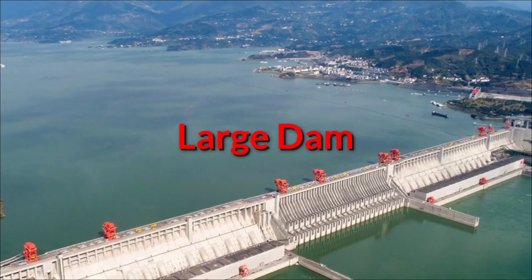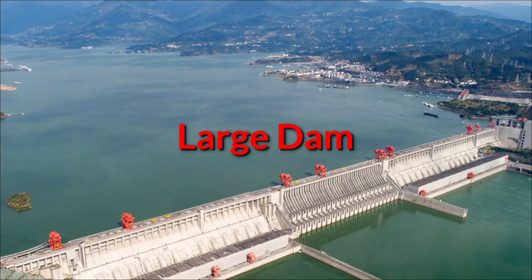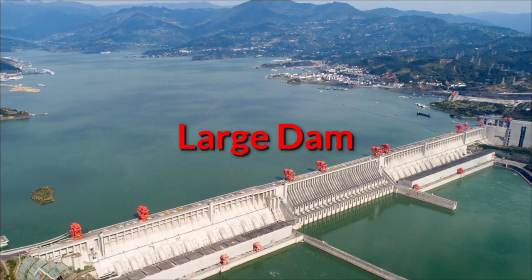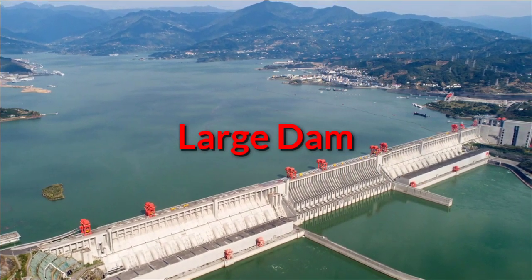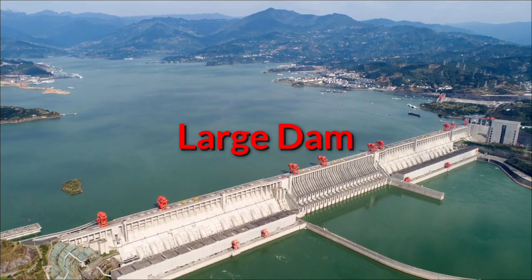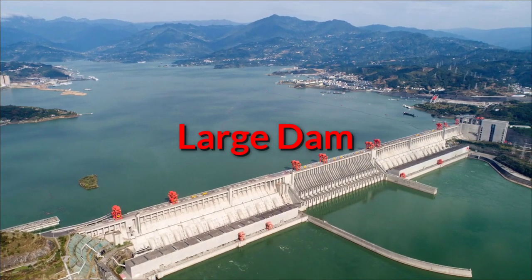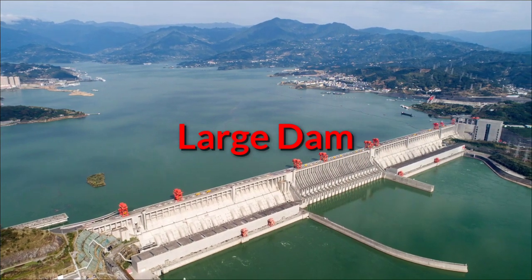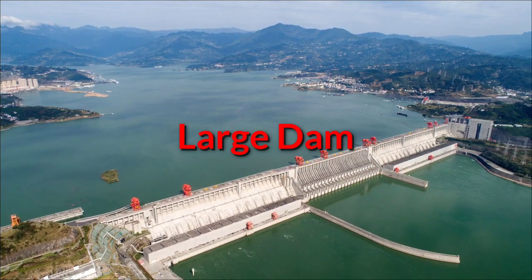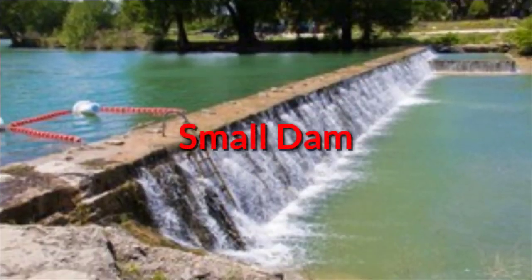For large dams, the International Commission on Large Dams defines a dam with a height of 15 meters or greater from the lowest foundation to the crest, or a dam between 5 meters and 15 meters impounding more than 3 million cubic meters of water, or a major dam over 150 meters in height. The reports of the commission also include dams between 5 and 15 meters high, or with a reservoir capacity of more than 3 million cubic meters, in the large dam category.